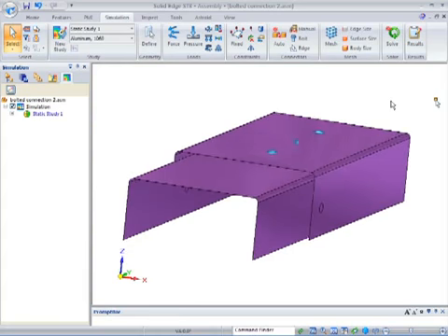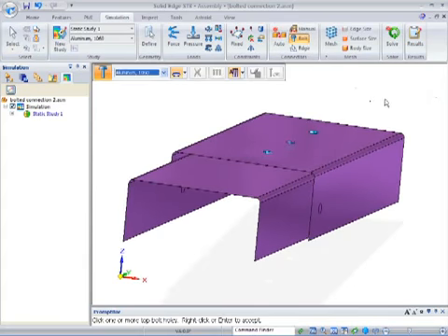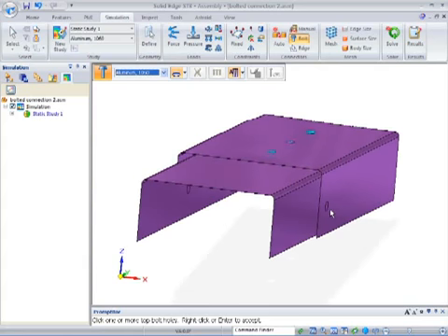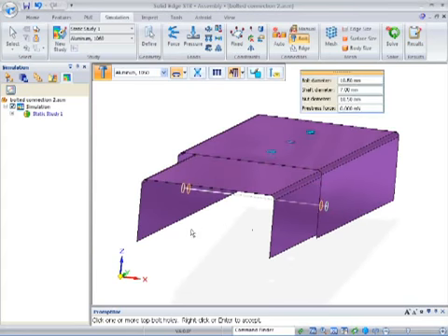And you can see where it's going to build the rigid elements to connect to the mesh when the mesh is created. Now I've got the 2 bolts on the side I need to deal with, so I'm going to go ahead and click on the bolted connection again, and this time I'm just going to select the one hole, and what it does is it's going to search out whatever's in line with that hole, thinking the user might want to bolt this all with one bolt. But in this case I want 2 separate bolts, one on each side.